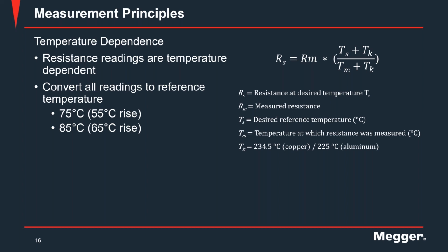Yes, thank you, Samir. So in that case, when you start, let's say, very early in the morning, and of course the ambient temperature starts to increase, remember that, especially for larger transformers, the time it takes for the internal part, in this case the windings, to reach equilibrium with the ambient temperature is too long compared to the time that you take to actually run your measurements. Now, you can tell me maybe we come in the morning, we do the low side, and for whatever reason, we don't get to do the high side until late afternoon when the temperature already changed. Of course, then for your high side measurements, you look at your winding gauge again, take that reading and use that for your calculation to convert back to your reference temperature.